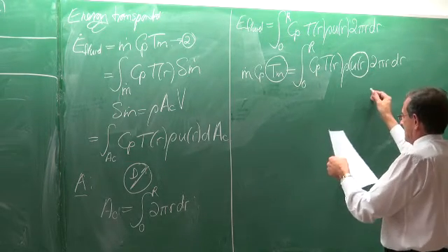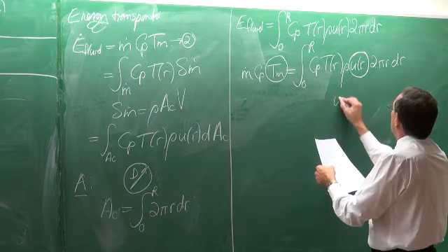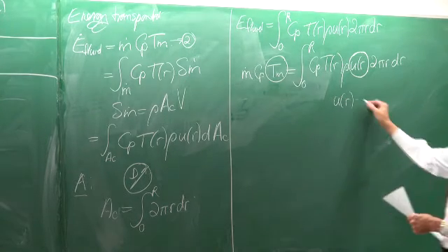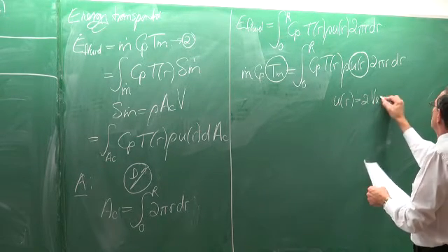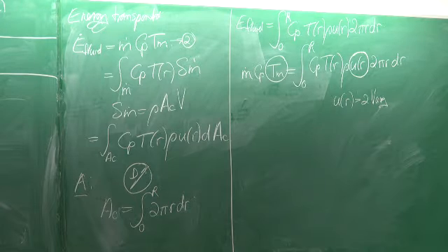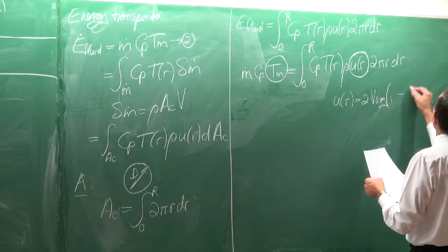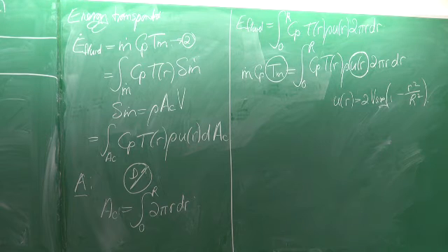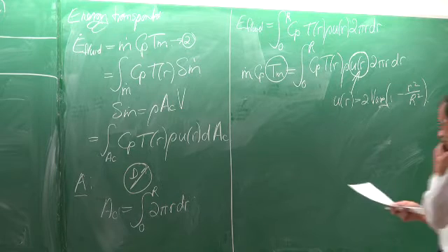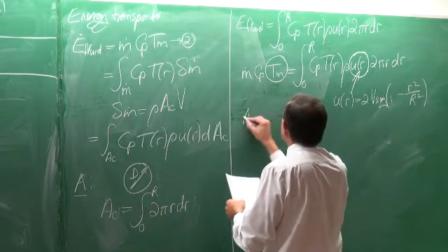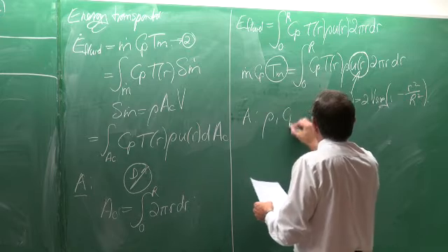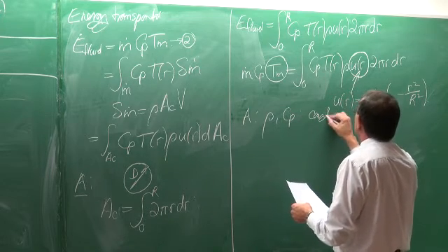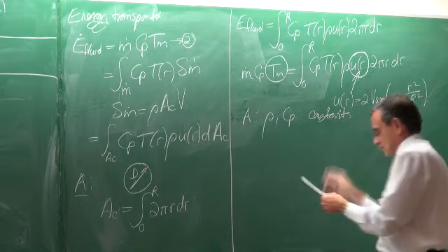Okay. And now, remember, that is from equation 1, where we've got the velocity as a function of r is equal to 2 times the average velocity multiplied by 1 minus small r squared divided by capital R squared. And if you put that in there and clean it up a little bit, it is all in the textbook, so you can go and do it at home, making the assumptions that the viscosity and Cp are constants. Okay.